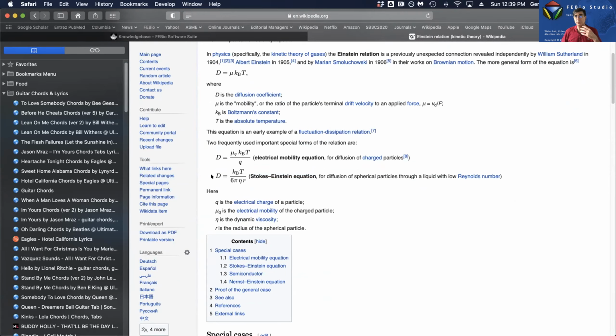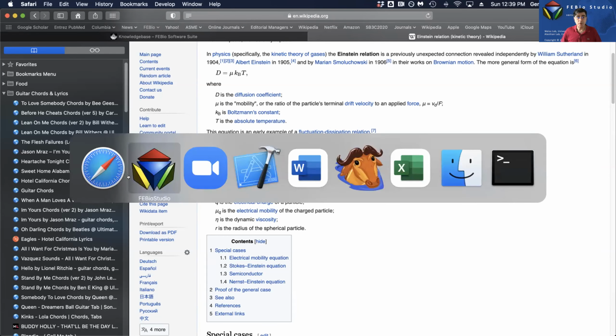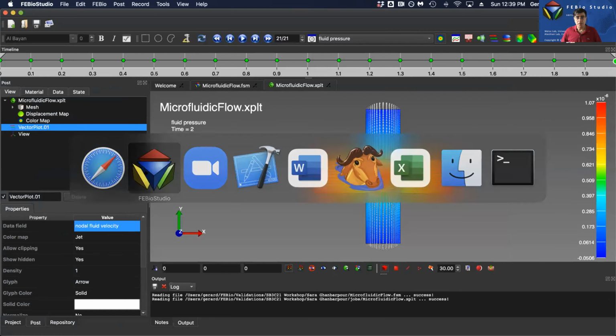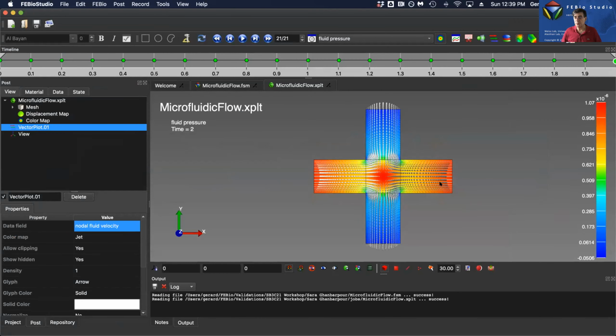Then you run a fluid solute analysis, which currently is not yet available in FEBio. This is the missing part. It's not currently available using a viscous fluid. You can do it using a multiphasic material, but then it'll be a different behavior. So as a result, you would need to wait until we release the fluid solutes module, and I'm giving a presentation at the conference tomorrow on that module. Anyway, then you would be able to track the particle as it flows through.